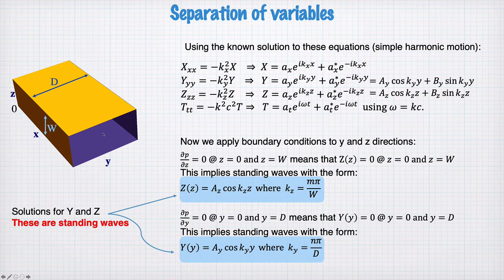In addition to the standing wave, to get a mode that propagates along the waveguide in the x direction, we can add a travelling wave component to these, and then we have these waves where they have some sort of mode shape in the transverse direction, the y or the z direction, and propagate along the x direction. And that's how we construct these modes of the waveguide. But the basis underlying all of this is that in the y and z directions we have these quantized standing waves.